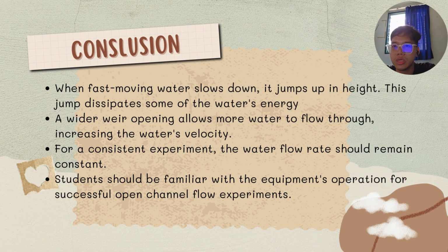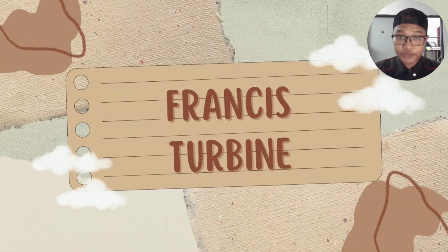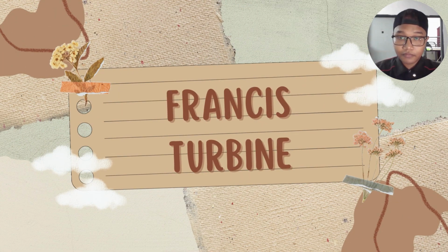This is a conclusion. When fast moving water slows down, it jumps up in height. This jump dissipates some of the water energy. A wide opening allows more water to flow through, increasing the water velocity. For a consistent experiment, the water flow rate should remain constant. So, next is the Francis turbine.